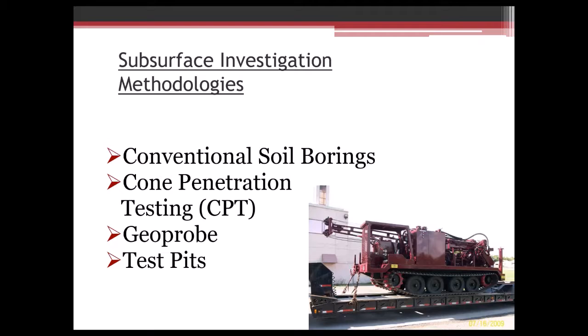So after we determine how many borings we're going to be doing and what depths we're going to be advancing those borings to, then we determine the methods that we're using to get those, whether we're going to do conventional soil borings, cone penetration testing, using a geoprobe for various different things, or test pits.